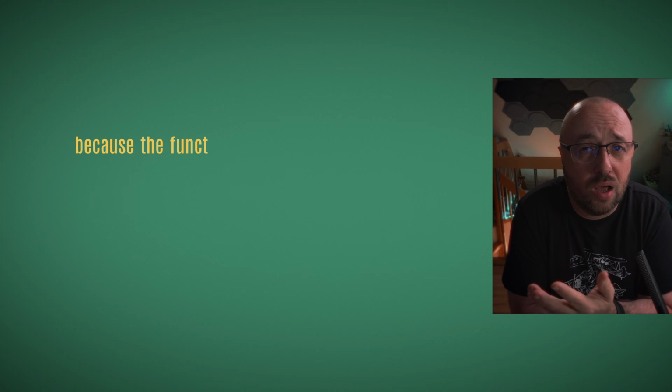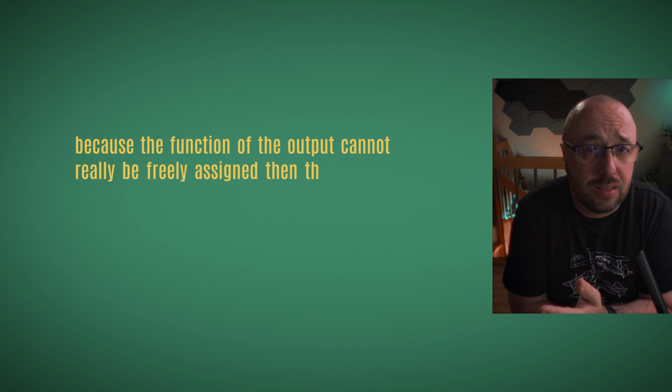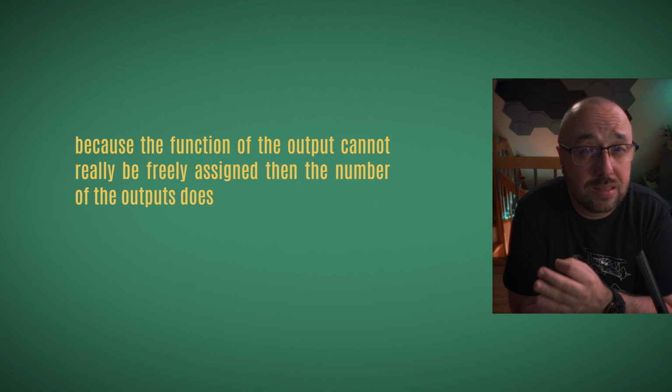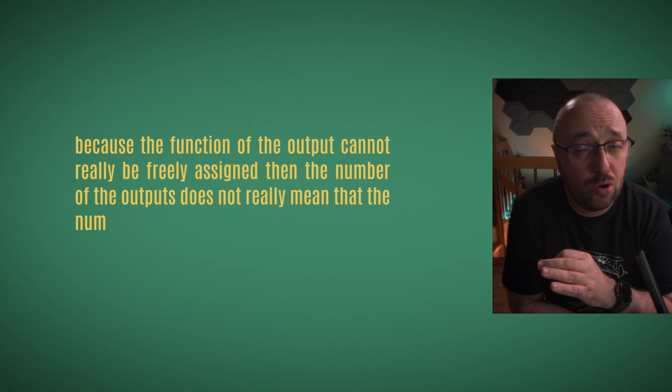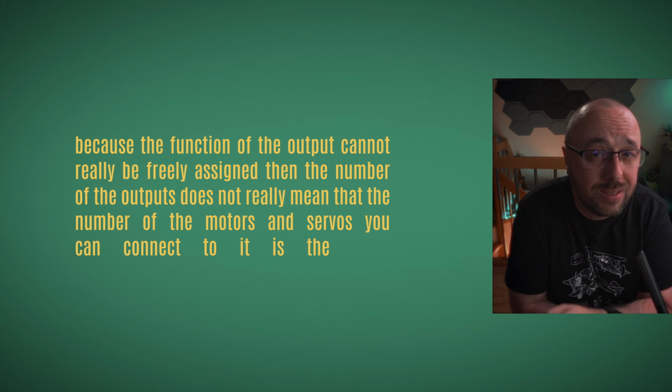And the fact that it has 8 outputs doesn't mean that it supports 8 motors. Always check the specification of the hardware you want to buy. A very similar situation is with airplanes. Because the function of the output cannot really be freely assigned, the number of outputs does not really mean that the number of motors and servos you can connect to it is the same.